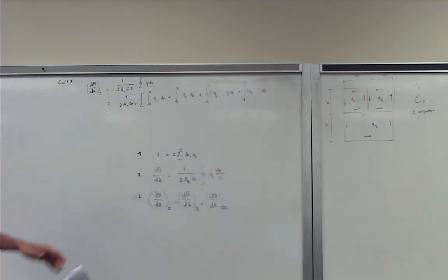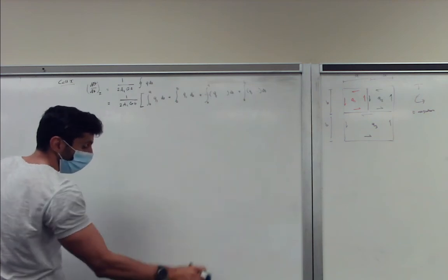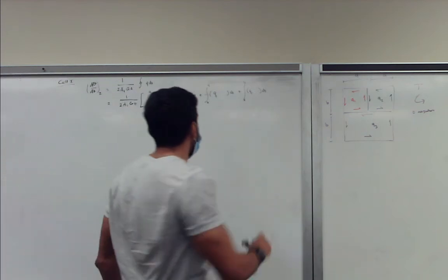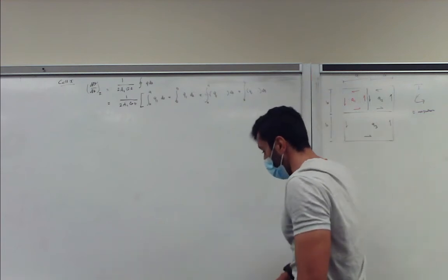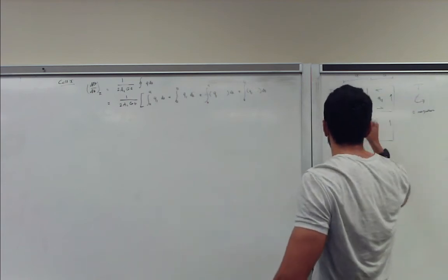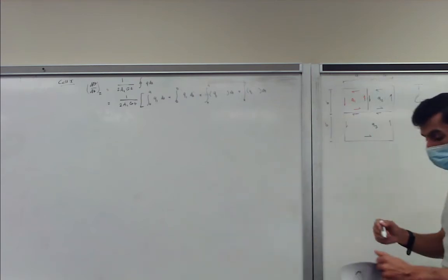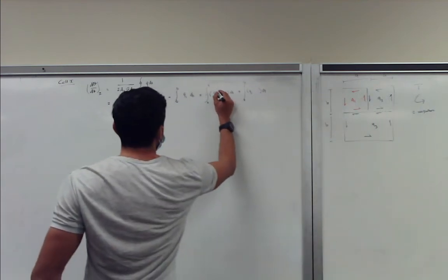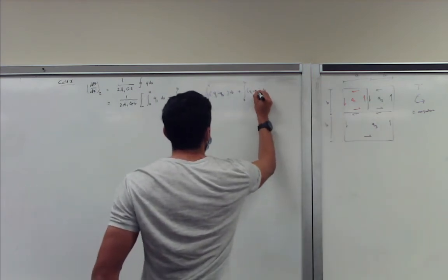So that's basically the shear flows due to the internal T1, cell 1. But in this case, if we look at this in a bit more detail, we will have Q1 going from left to right, and on the same cell segment there will be a Q3 going from right to left. So we have to take that into account, so we have to subtract Q3 here, and similarly, we have to subtract Q2 from that one.